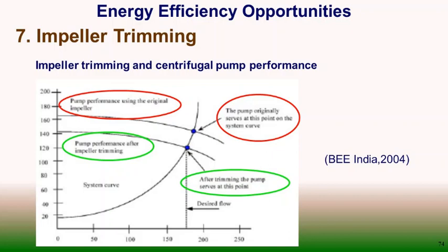The balance of the pump is maintained, and impeller trimming should be done from all sides. Changing the impeller itself is sometimes a better option than trimming, but we have to see which one is the economic option, and we have to see the effects depending upon the desired performance. So all these things have to be balanced before we choose to go for impeller trimming.